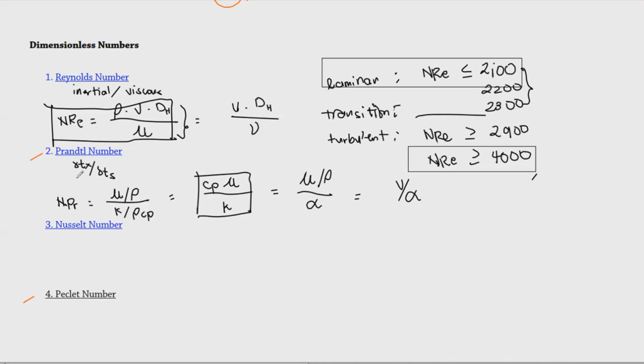Now, the Nusselt number is also a very important dimensionless number, since it gives us the relationship of the Reynolds and Prandtl numbers. Usually, when we talk about the Nusselt number, it is a function of the Reynolds and Prandtl numbers. So this is usually how it goes. There are a lot of correlations that give us the Nusselt number, and this one would simply give us the ratio of the resistance to heat flow by conduction and the resistance to heat flow by convection.